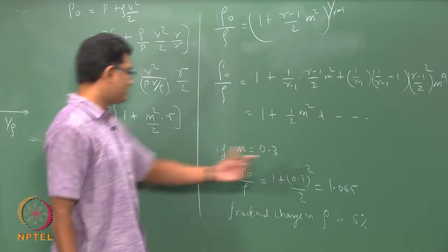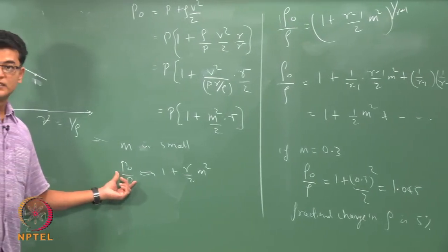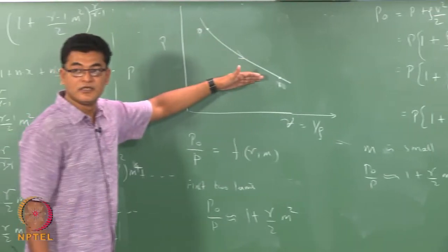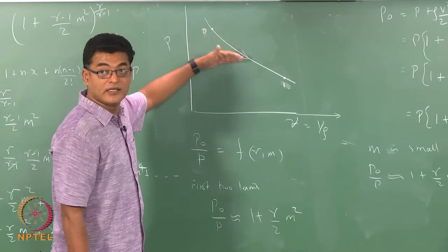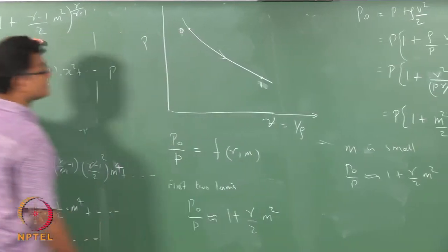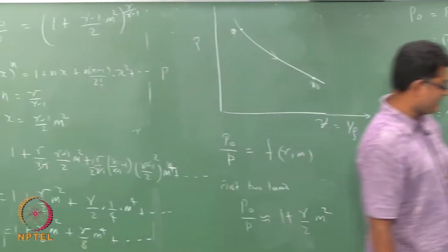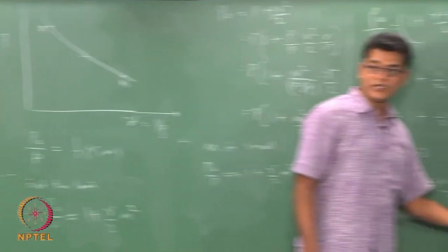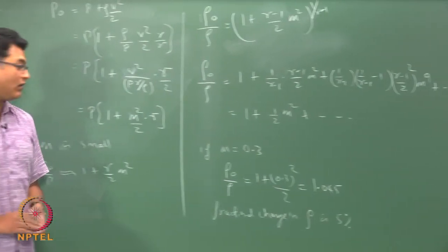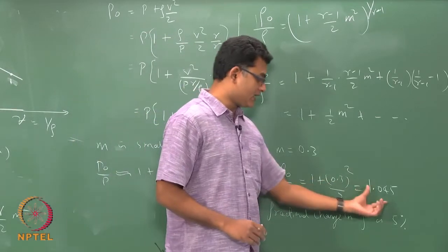Okay. So if I use that 0.3 here, then my fractional change in pressure when I do this process is equivalent to what you get from Bernoulli's equation instead of using this. That is the point. If I decide I cannot accommodate 5%, I can only accept 1%, or I can extend it to say 20%, then this would be quite large.